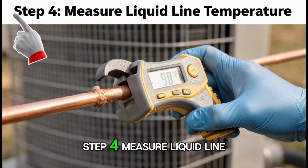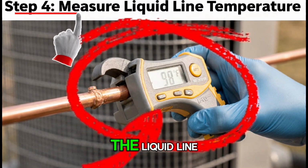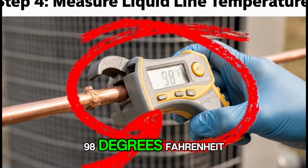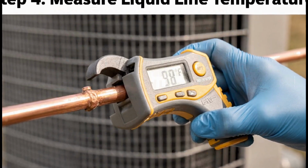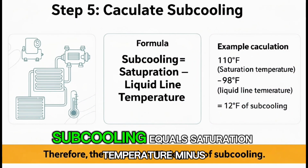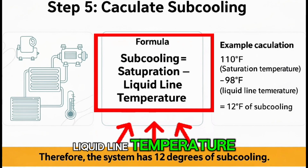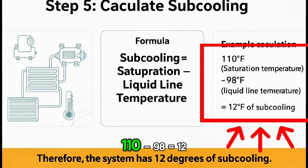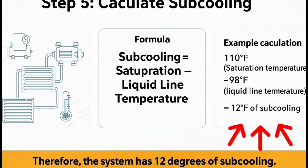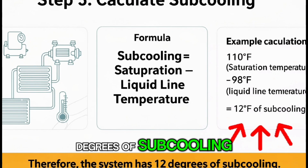Step 4. Measure liquid line temperature. Use a clamp thermometer on the liquid line. Suppose the actual temperature is 98 degrees Fahrenheit. Step 5. Calculate subcooling formula. Subcooling equals saturation temperature minus liquid line temperature. 110 minus 98 equals 12 degrees Fahrenheit. Therefore, the system has 12 degrees of subcooling.